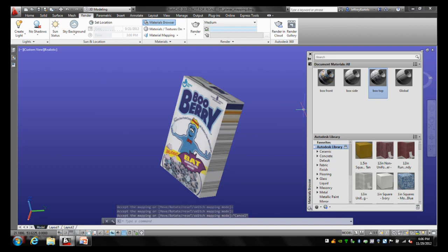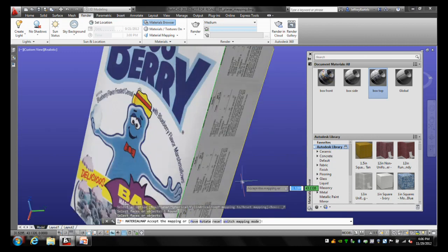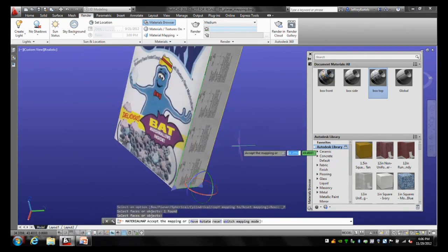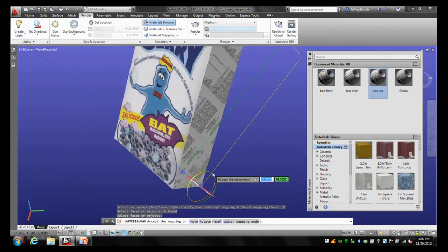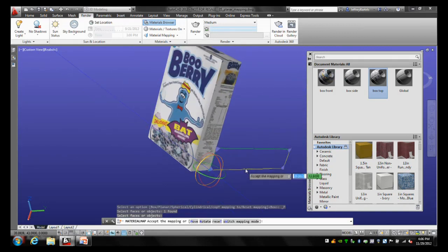All right. Let's do one more quick. We'll just do the side one here. Planar mapping, Control-click, hit Enter to square up the material. And then in this case, looks like we just have to rotate it. I'll select the ribbon, and I'll rotate this 90 degrees via eyeball.